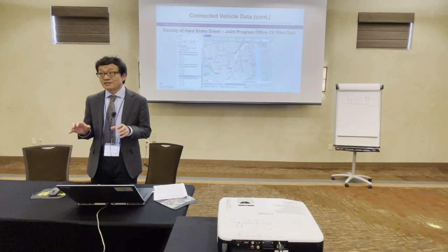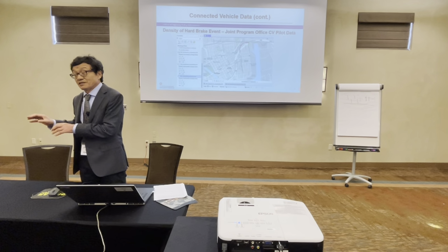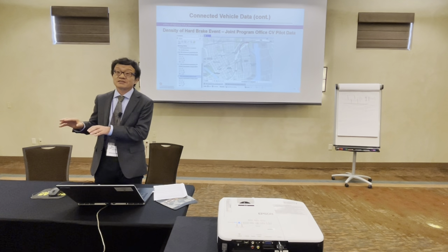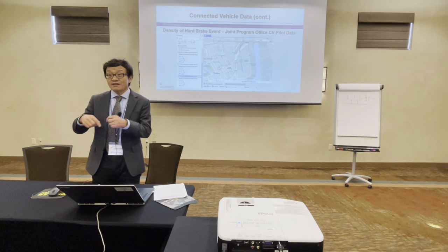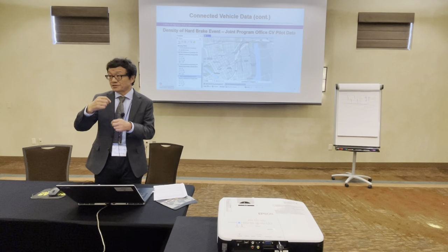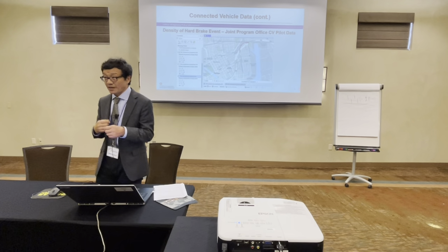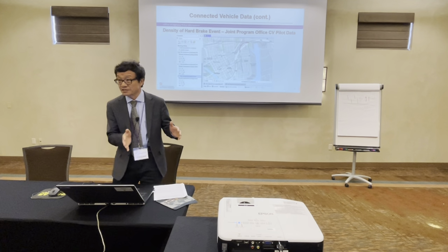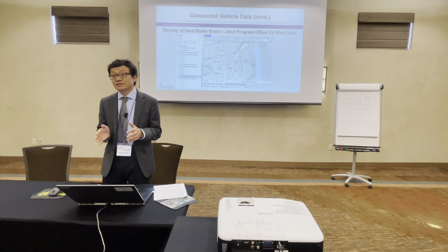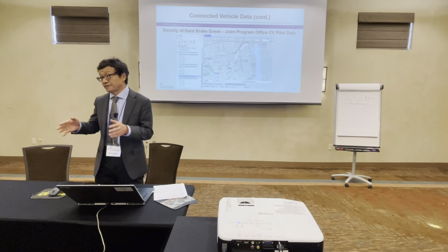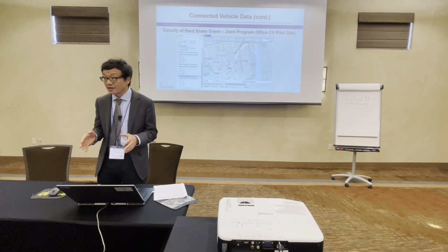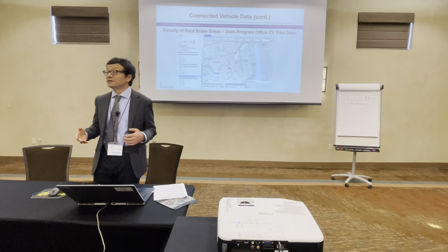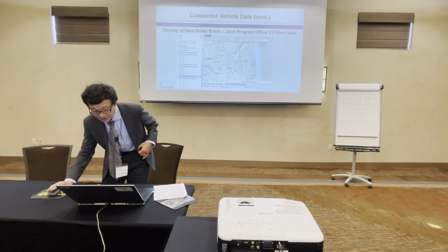One type of safety data that connected vehicles broadcast out, we call a basic safety message. Whenever the speed of the vehicle changes, either accelerating or decelerating, or if you change lanes, which causes the lateral acceleration to change, it will broadcast that kind of information as a BSM to the surroundings, so other cars can know the safety situation.